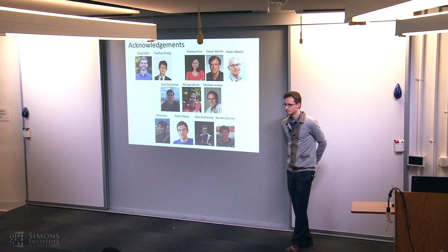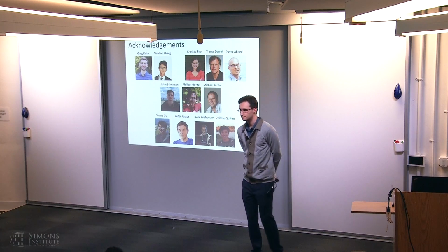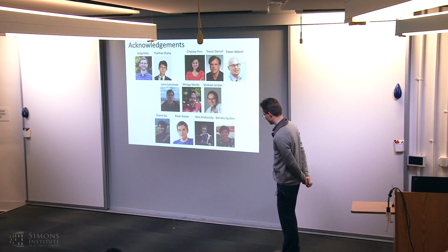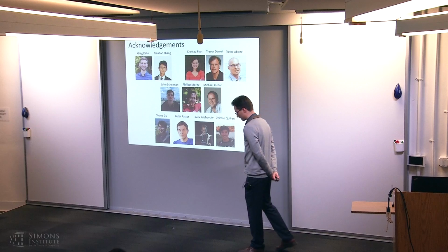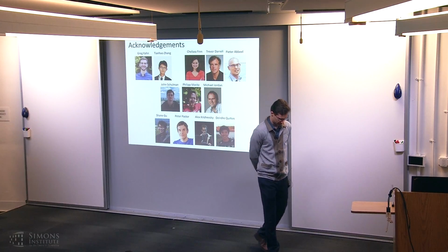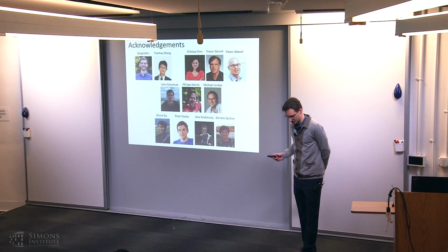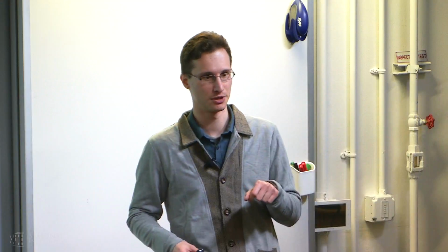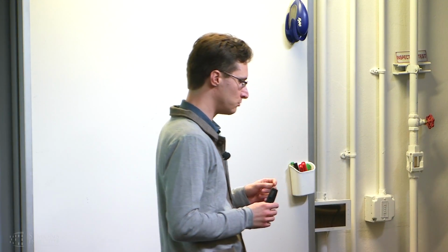Yes? The fact that robots are acting slowly, is it because of the optimization that is running in the background? Okay, that's a good question. Especially the robot that I showed in the beginning opening the door was moving very slowly. There are a few reasons for this. In the case of the video from the DARPA Robotics Challenge, there's a very practical reason, which is that there's a bunch of people sitting in a back room approving every decision, so they don't want it to go too fast.